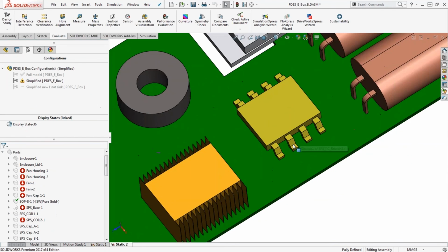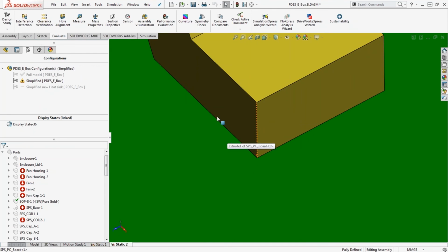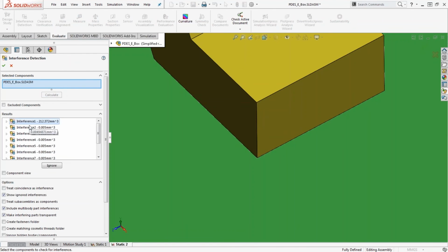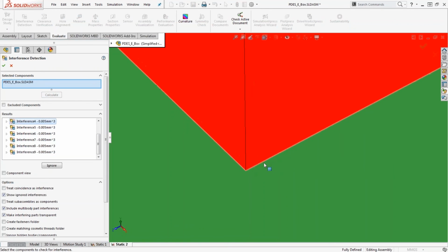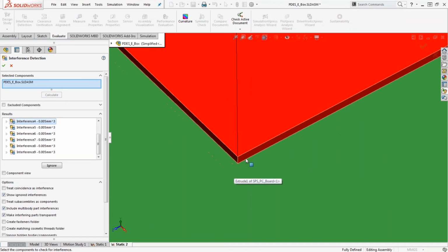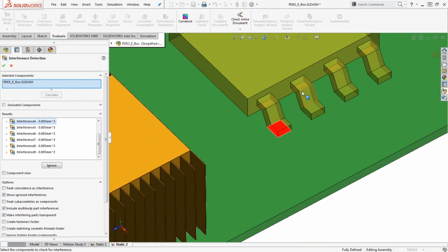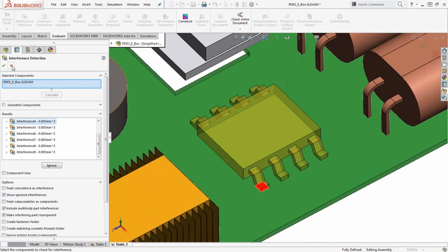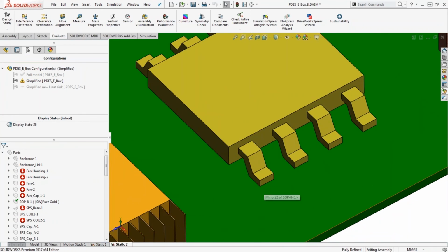All right, so how do we fix that? The easiest way is most likely there is a coincident mate that's mating the faces of the chip to the actual PCB. So you can just adjust your mate and then get rid of that interference. There may be situations though, however, where that's just not really feasible. Well, what you can do is physically remove the shared volume that those 2 components are having within that interference and actually physically cut that material off of the geometry.